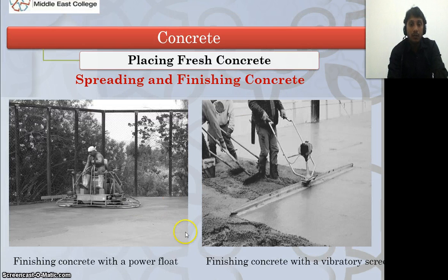So see, this is finishing concrete with a vibratory screed. This is finishing concrete with a power float. So everything after the concrete has been laid, it has to be leveled properly, it has to be spread properly, it has to be vibrated properly.